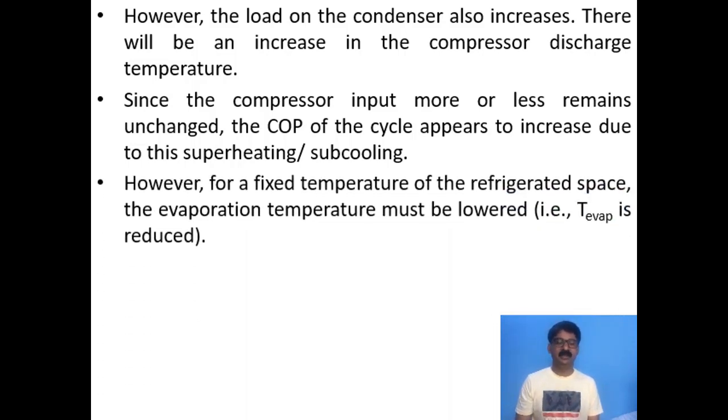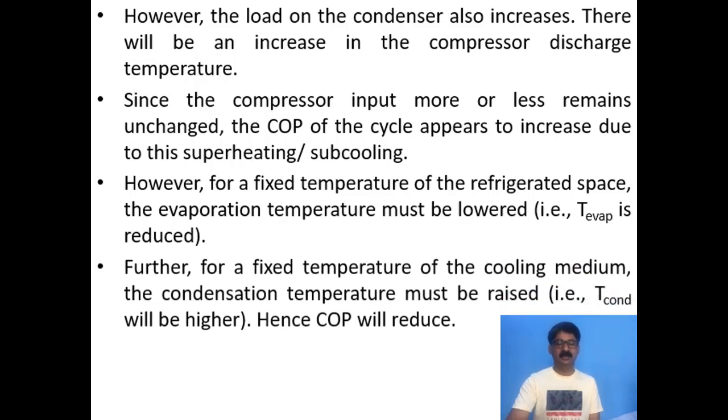However, for a fixed temperature of the refrigerated space, the evaporation temperature must be lowered. So for a fixed temperature of the refrigerated space, T evaporation gets reduced because of this subcooling and superheating. Further, for a fixed temperature of the cooling media, the condensation temperature must be raised. So T condensation will be higher, and hence COP will reduce.